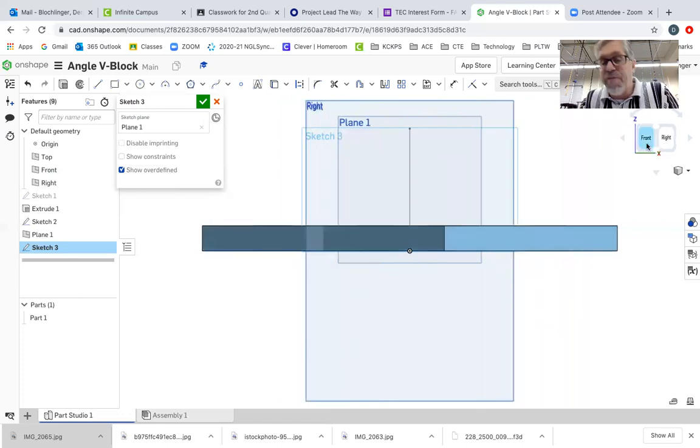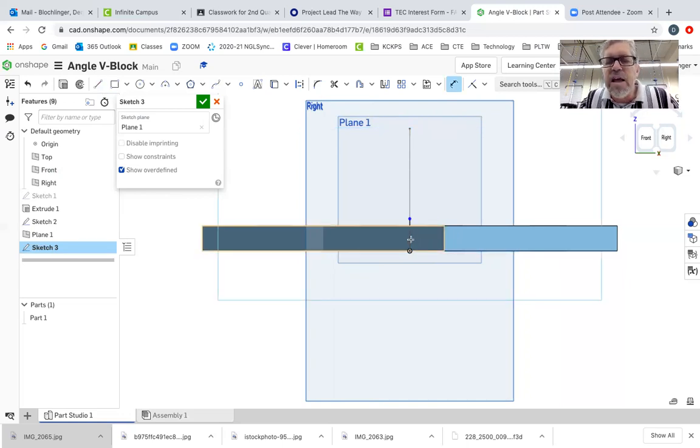Okay, that's close enough for us to draw, right? So now I need to draw on this object. I need to draw an L for line from our start point to this surface. What if I drew it? It's not snapping to it, right? So everything starts from there. I'm going to draw it nice and long, and then I'll do a D for dimension to get that point. Okay, and I know that the thickness of the base is 0.5, right?